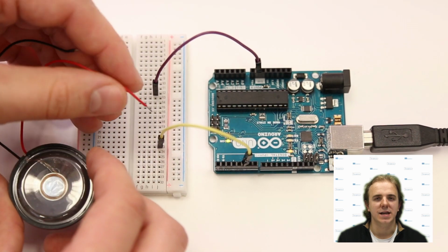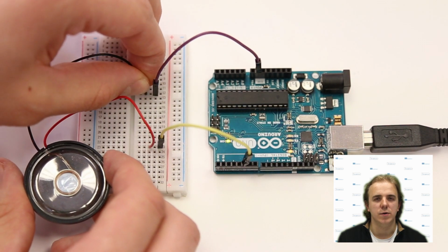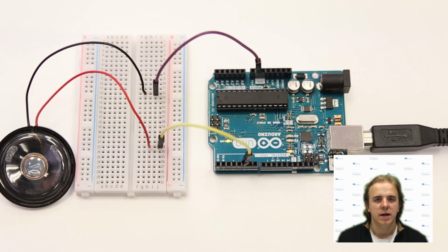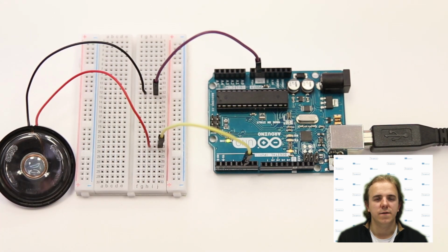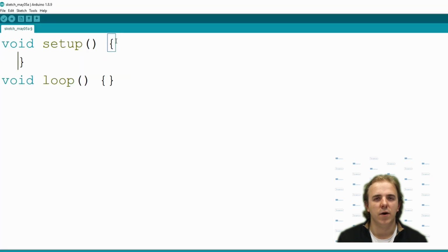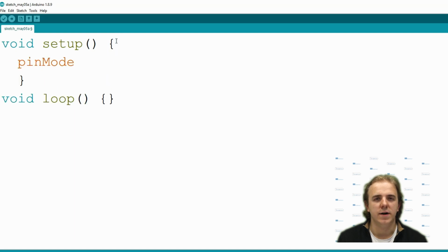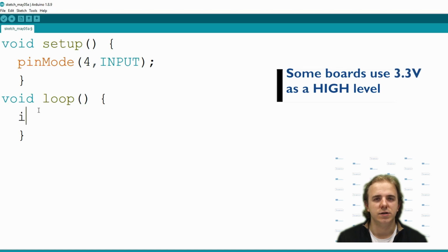You can replace LED with speaker between pin and ground, and it should make a sound. Different PWM values will give different tones. If you configure your pin as an input, you can use digital read and analog read functions. Digital read reads voltage values that correspond to either logical high or low values. In the circuit, these voltages usually are 5 and 0 volts.